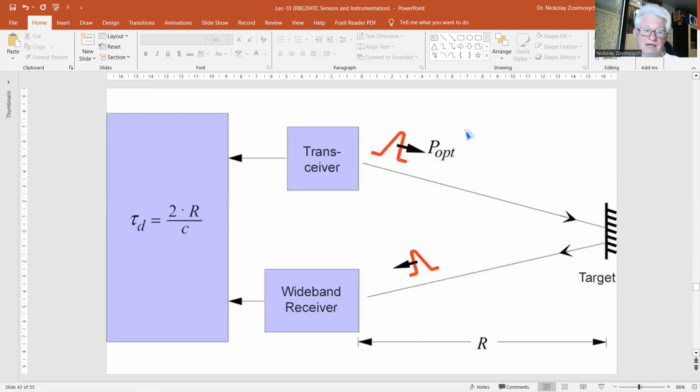A well-known application of the optical TOF principle is found in laser guns that measure the car speed. Usually, these systems emit a series of short pulses. From the TOF of the reflected pulses, both distance and velocity of the vehicle can be derived. Typical range and accuracy are from 5 to 500 meters, plus minus 2 kilometers per hour.